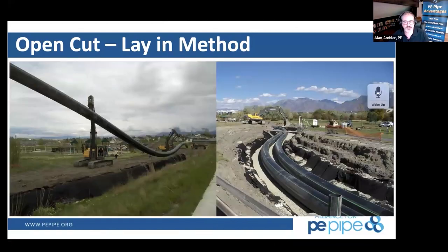Here's that picture again on the right. So that contractor knew that they could open up a longer, larger area, and they're starting to make use of that as well. So you'd take advantage of the productivity tools to fuse up runs above ground in a laydown yard, either close to the project site or within applicable distance that you could pull that into place. And then you start to fuse up that long run, open your excavations as we go through, simply drop that pipe into the excavated hole and start to move forward from there.